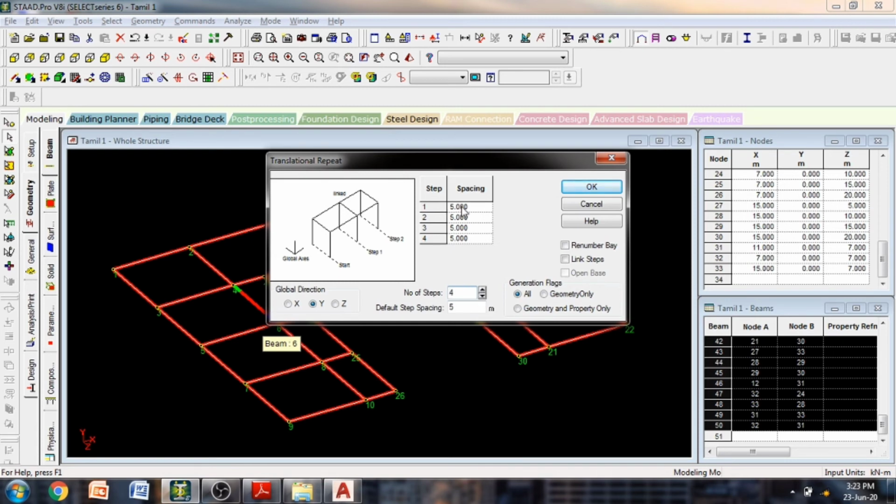This is the ground floor's bottom layer, and this is the roof of the ground floor, this is the roof of first floor, and this is the roof of second floor. Now I cannot provide evenly because I don't need 5 meters of foundation. Probably 3 meters depth for the foundation is more than enough for me, and I'm assuming each and every floor has 4 meters. So 4 is enough for me.